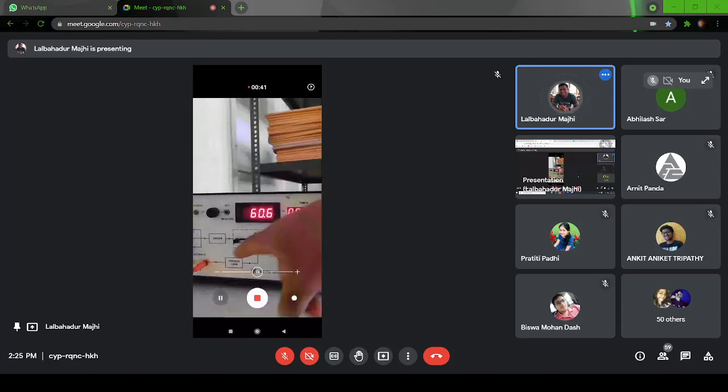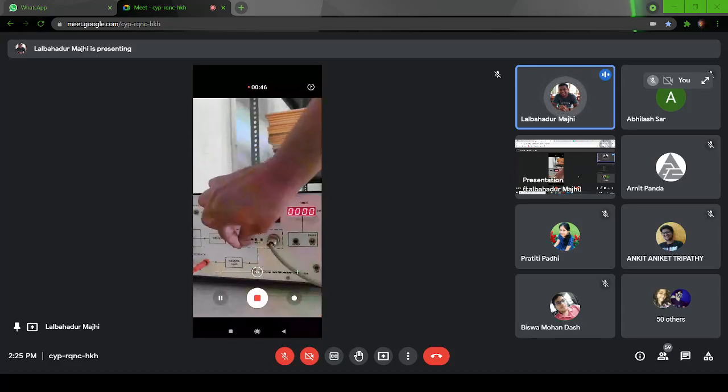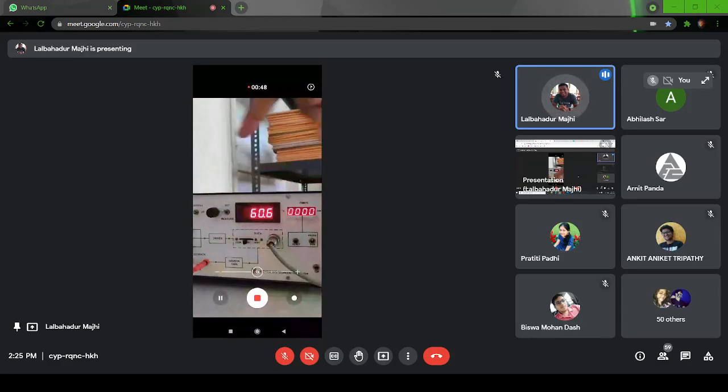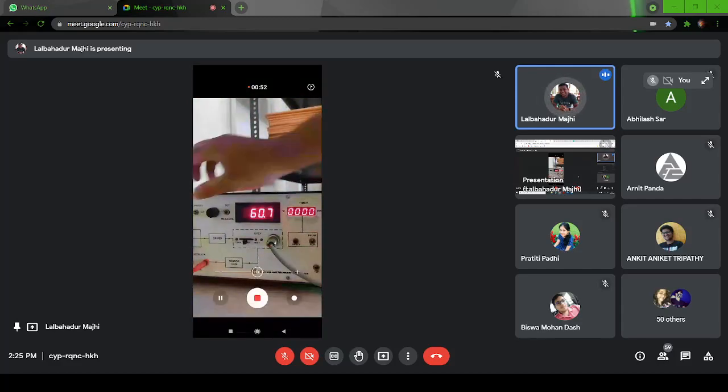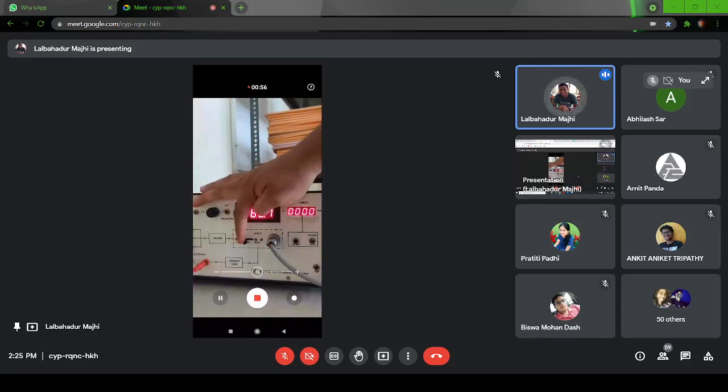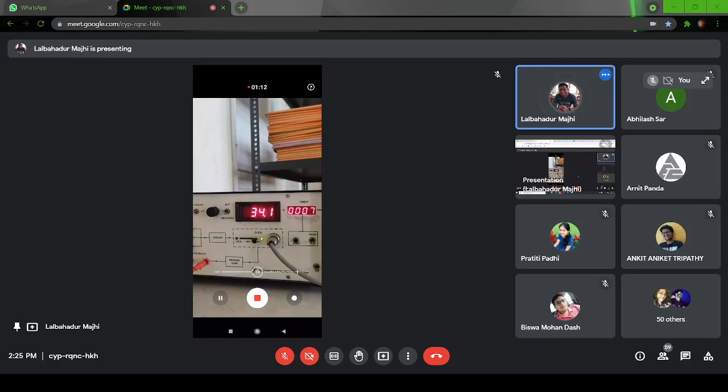Our oven is in cold, in cool position. This is the off position, then we will switch on. So this is on-off control; we have not connected the PID control. It is set in low. Now we heat the oven. This switch will heat the oven, and then we will measure the temperature and note the time. So note down in each 5 seconds what the temperature is.